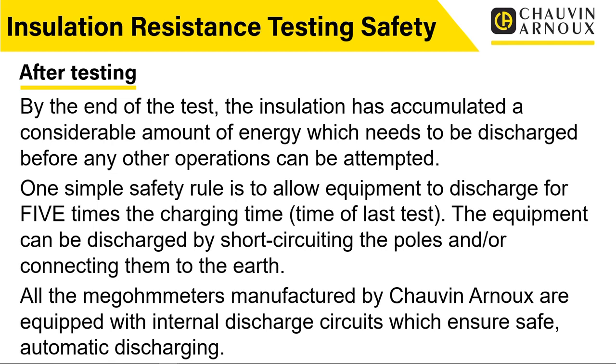Say you've locked the tester in the on position and you're moving the probe during the test sequence from conductor to conductor, while the test is still live and isn't discharging. The items you've touched are potentially still charged up until you discharge them. It'll only discharge when you finally stop the test, and it'll discharge whatever it's connected to.